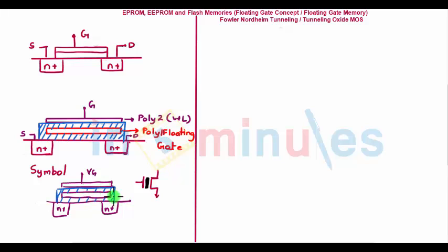Now the whole idea is that we are understanding the floating gate because we want to understand a memory type which is EEPROM, electrically programmable read-only memory. You can program this memory electrically, and when I say electrically, you need to do something with your voltages in order to program this memory. Though it does not erase your memory electrically, because there is no erase word in the name of EEPROM, you can still erase it in a different way. When you can erase and program it both electrically, it becomes electrically erasable programmable read-only memory, which we would also see. This is a symbol for the floating gate.